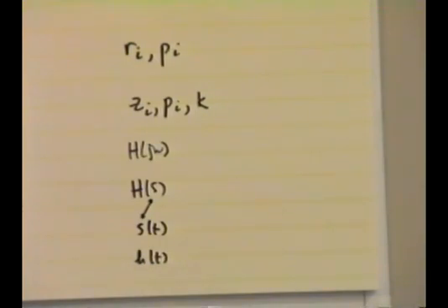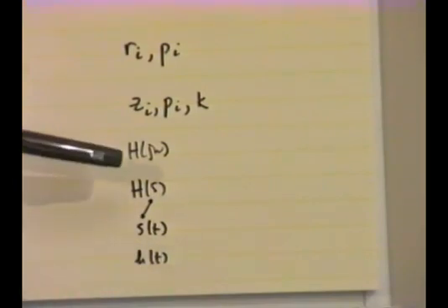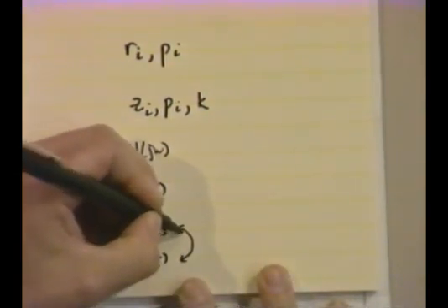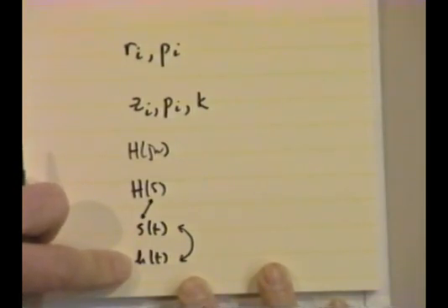And what's important is for you to have both the specific skills of going back and forth between these, as well as some general ideas of how these things fit together. So, for example, to take these two, how is H related to S? If I gave you the step response, what's H? It's a derivative. And if I give you H, what's S? It's the integral. Then there are interesting questions here. We have actually filled in the graph connecting these, several of the connections. Some of the others we haven't, and you might want to do that yourself just to work it out.